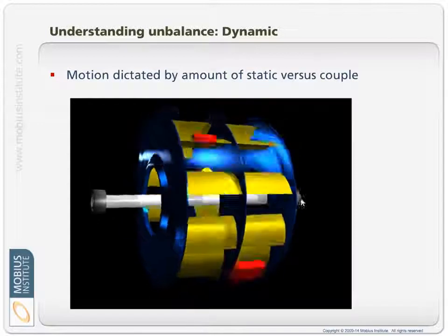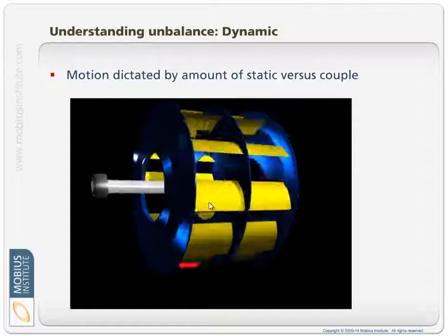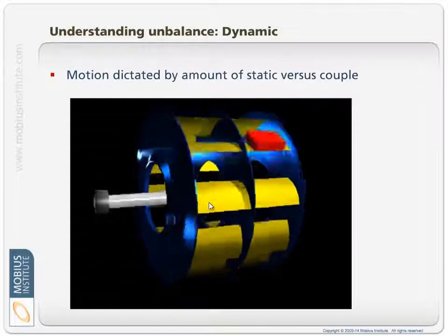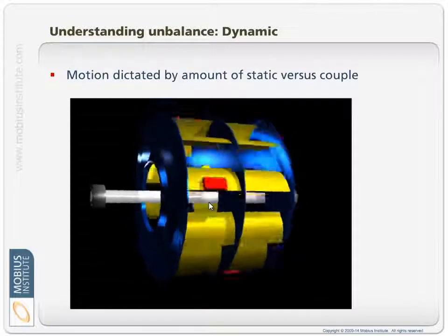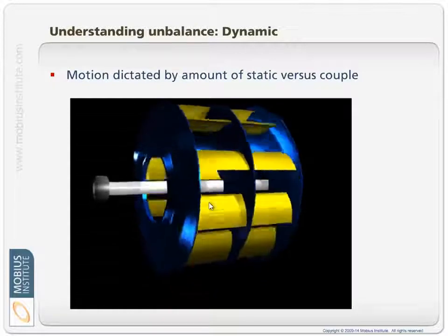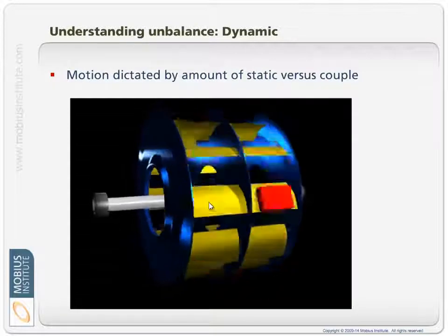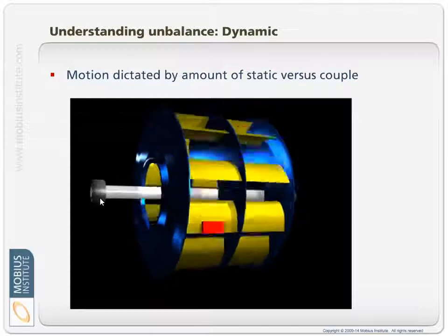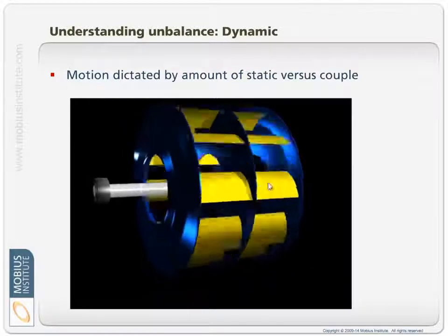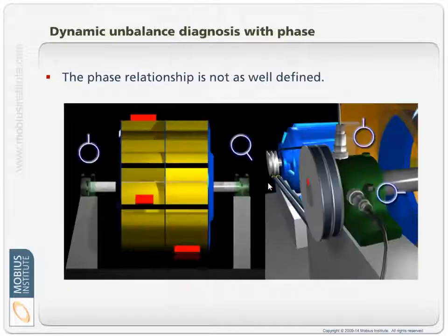Here we've got, call it dynamic unbalance. The rotor's longer, the distribution of dirt buildup along the fan is not uniform, so therefore, if you like, it's more out of balance in one plane than another. Either way, that is still circular motion, but from one end to the other, it's not in phase like it was just before.